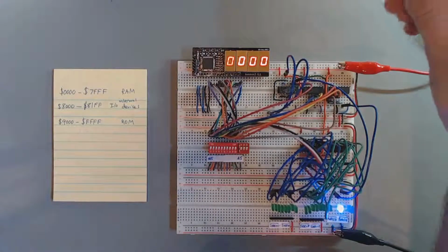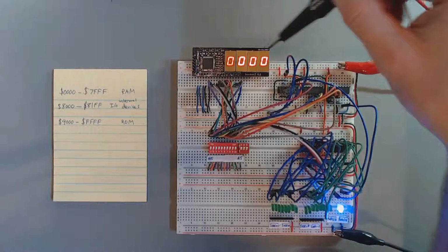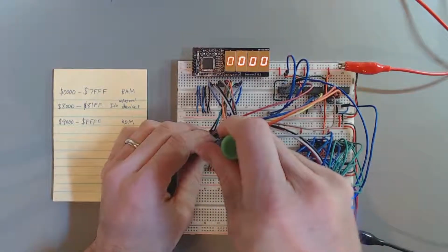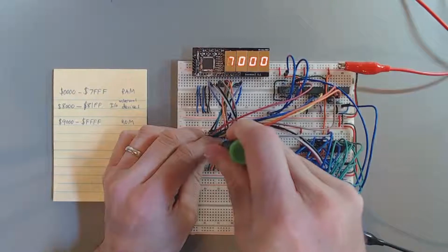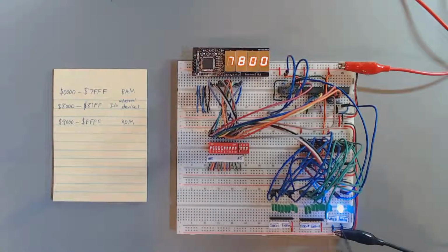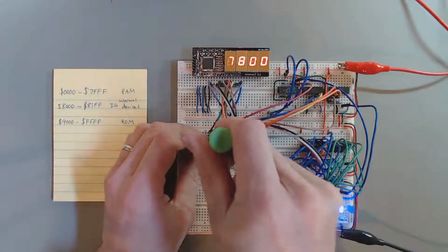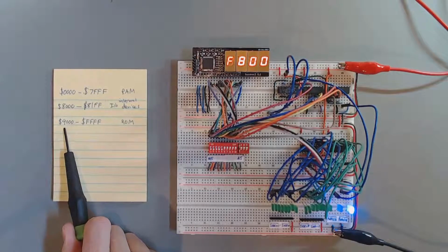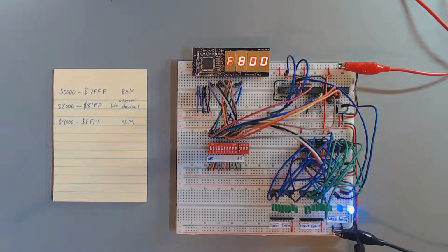All right, so let's generate some addresses and see what chip enables get asserted. So right now the address is 0 and the RAM enable is asserted. What you can notice is that regardless of what address bits are set to 1, as long as A15 is low, we're still going to be generating a RAM enable signal because all of those addresses correspond to the RAM device. However, when A15 goes high, now we're in the upper 32K of the address space. And as long as we are above the 4K I/O region, in other words, as long as the address is hex 9000 or above, now we're generating a ROM address, and the ROM's chip enable is going to be asserted.